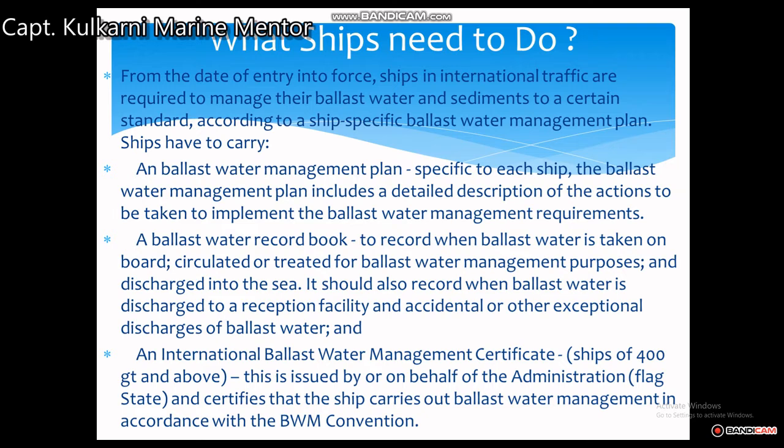Specific to each ship, the ballast water management plan includes a detailed description of the actions to be taken to implement the required ballast water management. A ballast water record book records when ballast water is taken on board, circulated or treated for ballast water management purposes, and discharged into the sea. It should also record when ballast water is discharged to a reception facility.